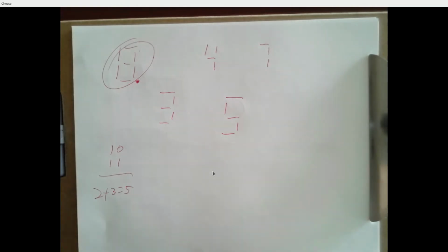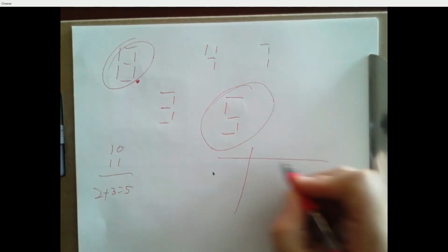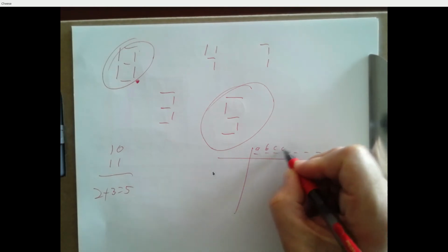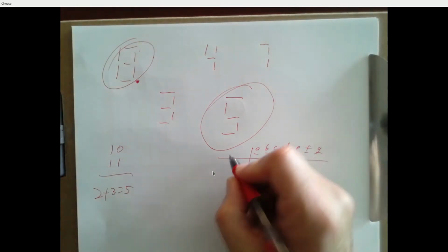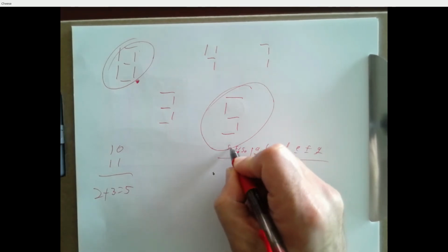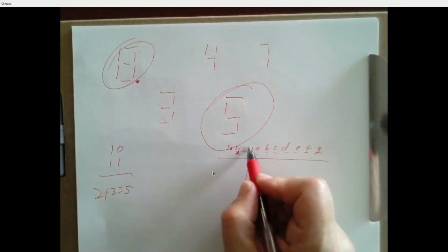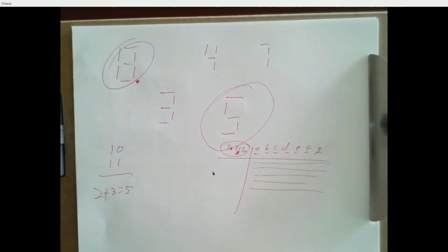So let's talk first of all about how we make this happen. We've got 7 segments here, so 7 outputs that we need to control, A through G. Depending on your input values, let me call them sum 0, sum 1, and sum 2, so 3 inputs, we want to turn these LEDs on or off accordingly.